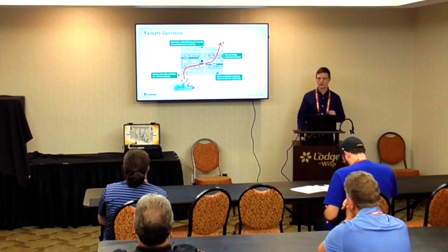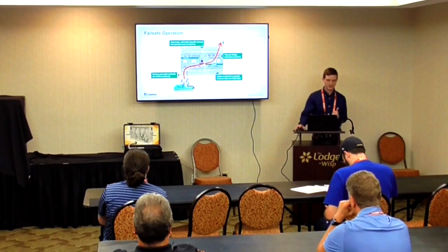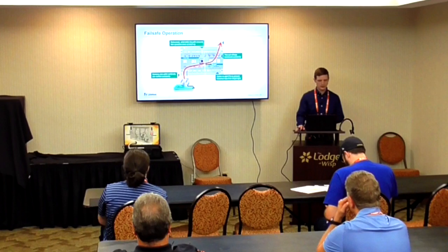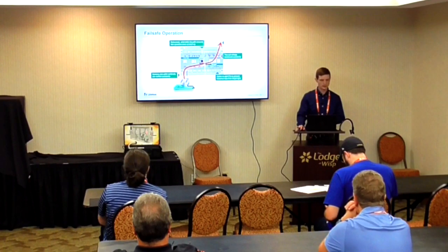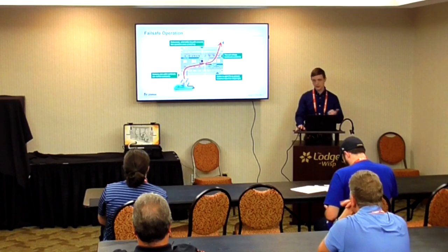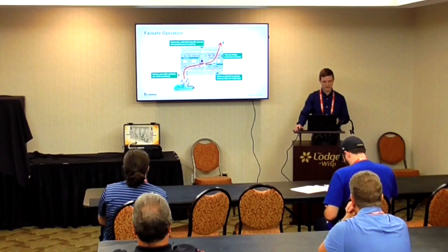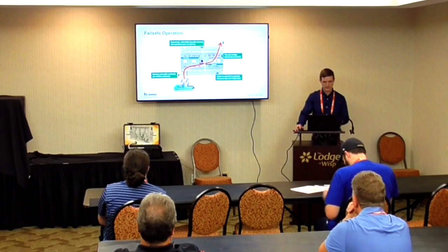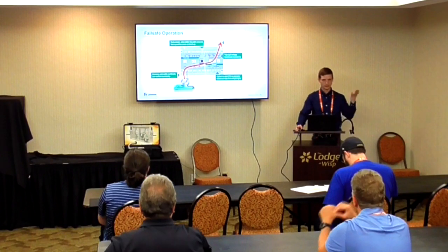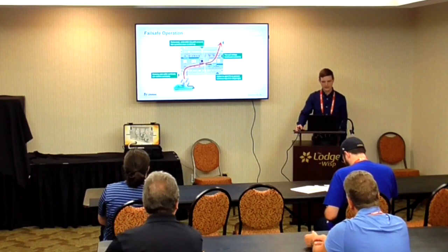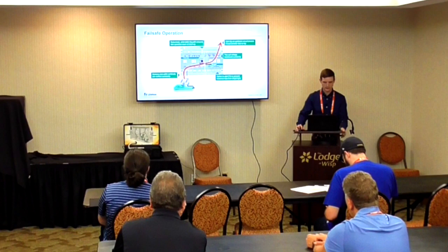Think of this as a kill switch if you're operating like a gantry or something heavy where you're constantly holding it in the on position. As long as you've got control power here, this contact is being held into position. So if the microprocessor on this thing gets damaged, if the unit itself gets hit with a forklift, or there's an arc flash in the enclosure that this thing exists in, or same thing goes back to those sensors, it'll automatically release that voltage, and then that's where you get your tripping.